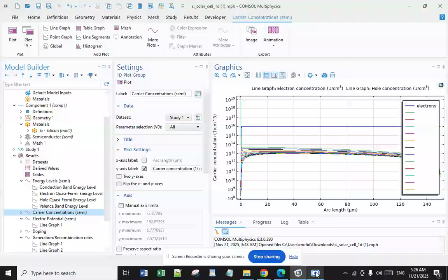And here, this simulation shows the arrangement of the unit cells, and it shows the atomic structure of single crystalline silicon. One can determine from this simulation that there are effectively 8 silicon atoms in the volume of the unit cell, when the lattice constant of crystal silicon is 5.4. One can easily calculate that there are approximately 5 multiplied by 10^22 silicon atoms per cubic centimeter. This simulation shows the crystalline silicon atomic structure with no foreign atoms.